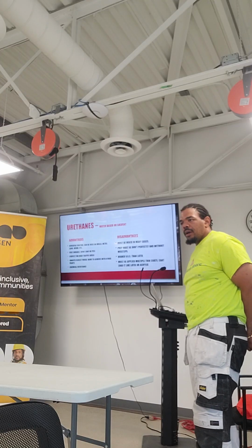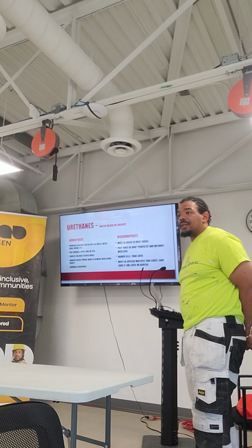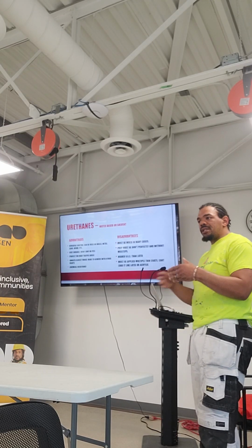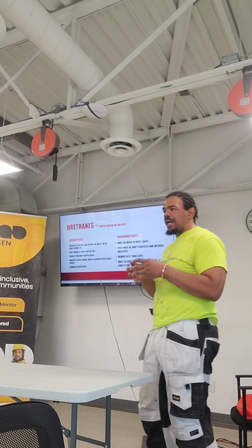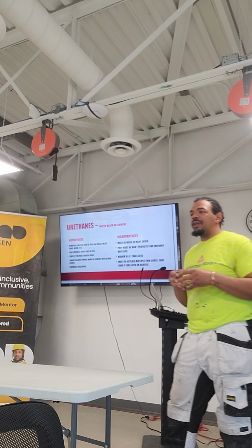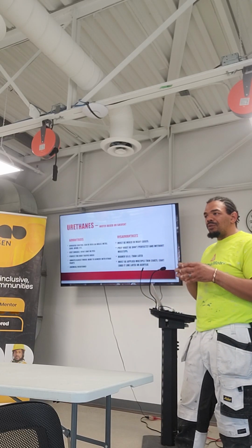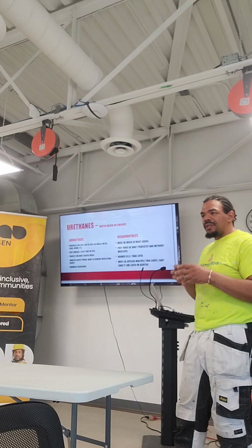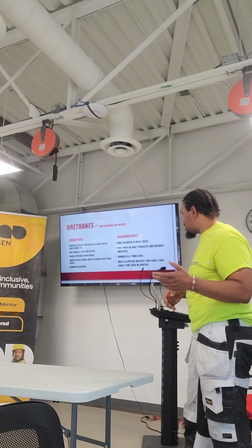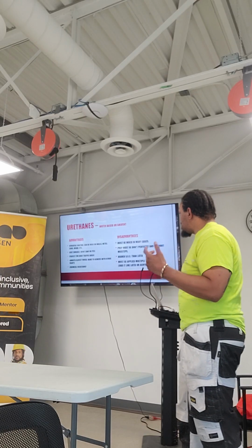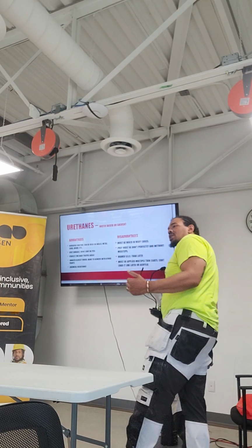2 part. Sometimes you have to let urethanes induce, which means after you mix them, you have to let them cook together and bind together in a chemical reaction. You have to let that chemical reaction happen over a certain amount of time before you apply the material. In some cases, but these urethanes are extremely durable.